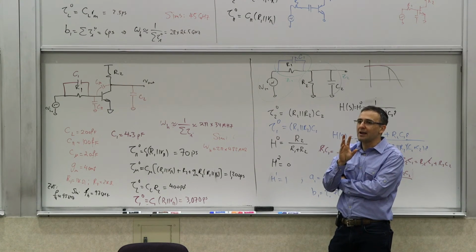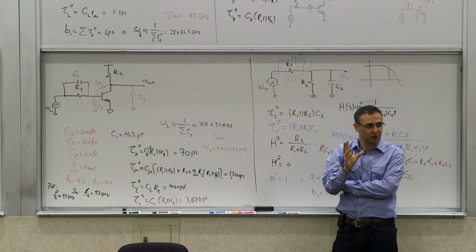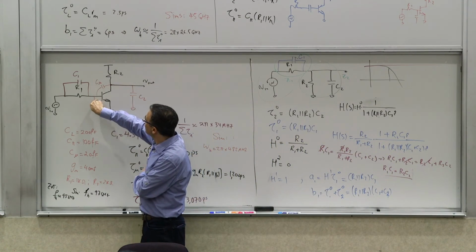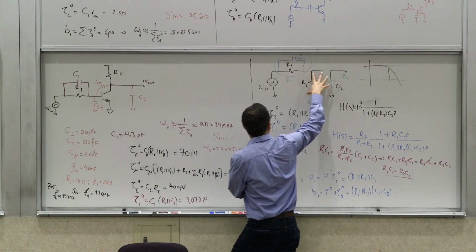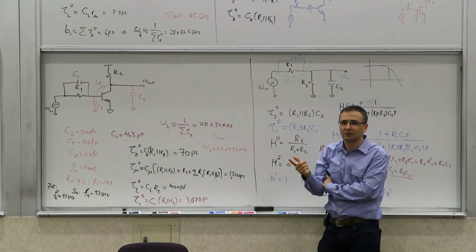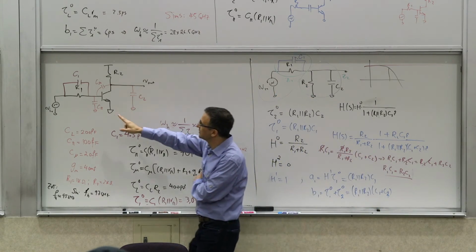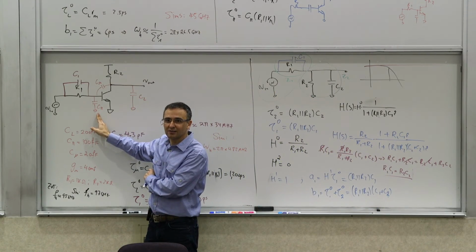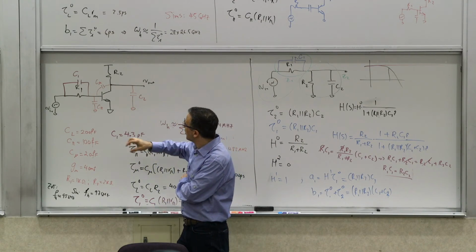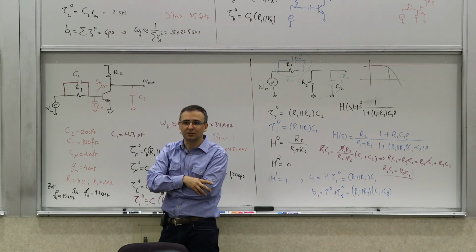What I could have done, or should have done, or did, is basically say, okay, what does this input look like in terms of an RC? What is the equivalent of R and C? The R part of it is simple, right? What is the equivalent of R2 here? R pi, right? What is the equivalent of C2 here? It's the total equivalent capacitance I see at the input.